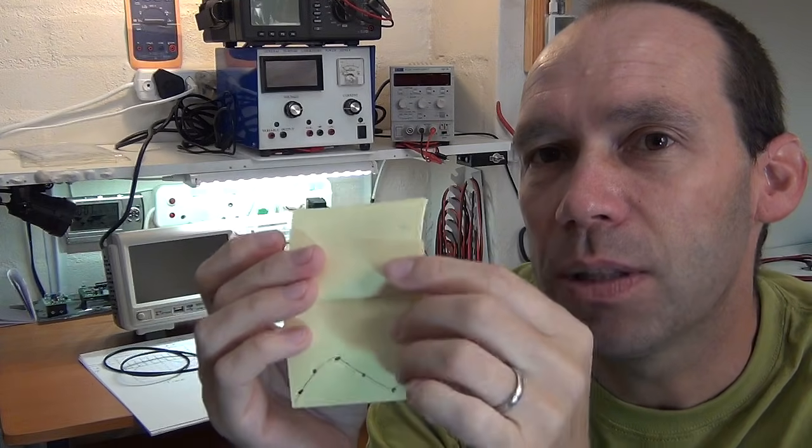In essence, your multimeter, if you can picture this as the screen, allows you a little sliver, a little slit window to look at a particular measurement, and if that measurement happens to be changing, you can only see an instantaneous value of that measurement changing. A multimeter is great if you've got a value which is reasonably constant and not changing much over time, because then you can see it instantaneously.